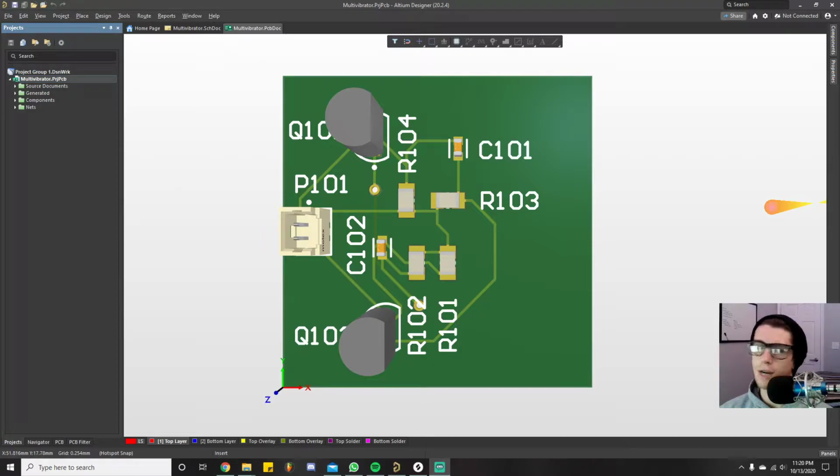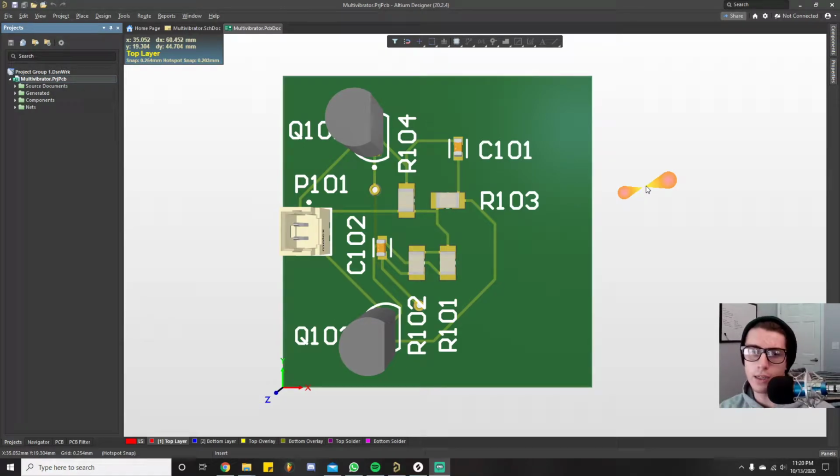In fact, pretty much every time you create these outputs and send them to a manufacturer, they'll have an engineer on the other end of the line, and they'll walk you through everything. They'll literally tell you everything you need. You can ask them, hey, I need some help, tell me what I need to do, and they'll say, oh look, we don't need the Gerber files, we need the ODB++ files or something like that. It's really easy to do a quick Google and figure out how to generate those, and you send them over, and the engineer will just tell you if something's missing. So don't worry, nothing bad is going to happen if you don't get it right the first time. Definitely don't be overwhelmed.